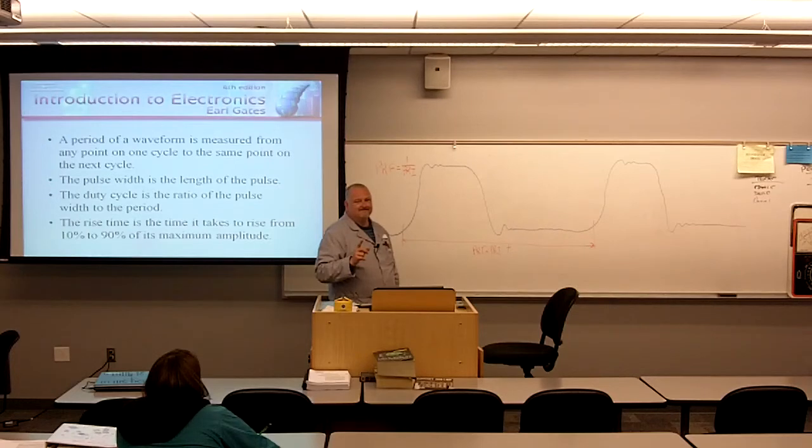Not reading the wave right, it looks like a perfect wave. Elaborate more. It's actually an easier answer. It's a one-word answer: harmonics. If you're sitting so close to an emission, that computer would pick up a harmonic and think the harmonic was the fundamental frequency, and it's not. The computer didn't know. The computer's only as good as it was programmed. So again, I wouldn't want to trust that.